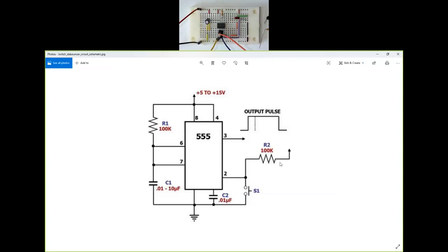I've connected the orange stripe to ground externally, and I'm going to connect the output of the 555 timer pin 3 to channel 2, the blue wire.